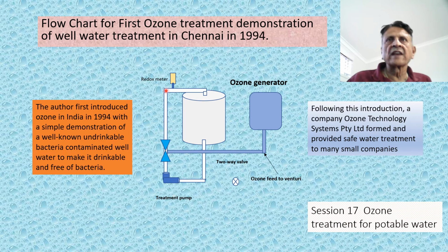Ozone continues to react until the redox level here had indicated 700 plus, which gives me the information that the water is sterile. At 700 plus, the bacteria cannot survive. So we try to ensure that redox levels exceed 750 millivolts when we complete the treatment.